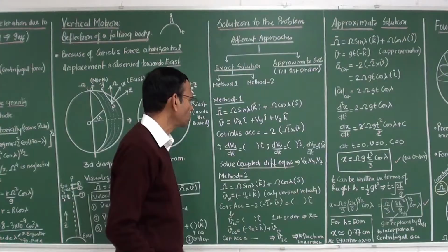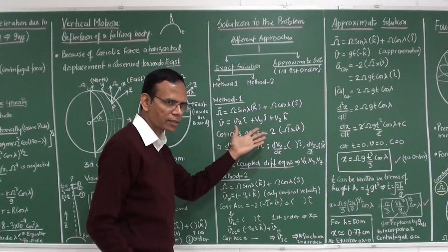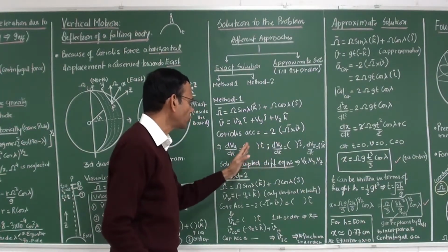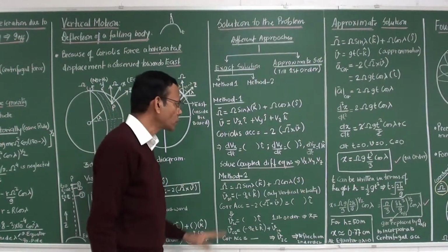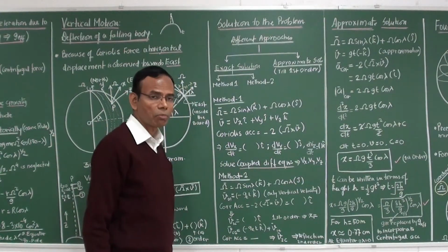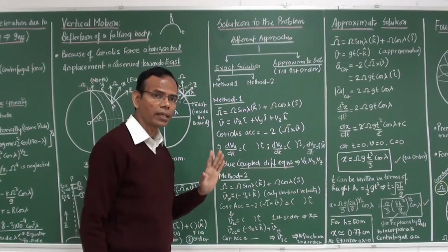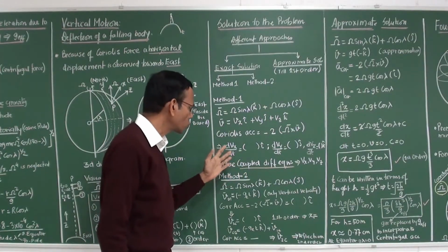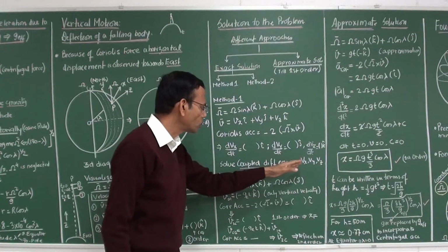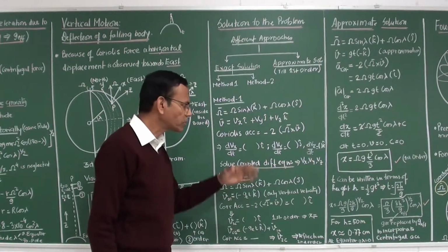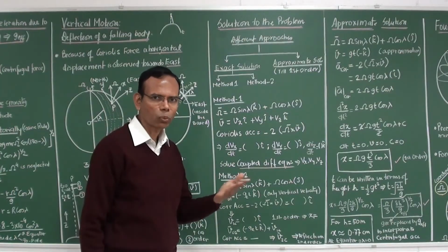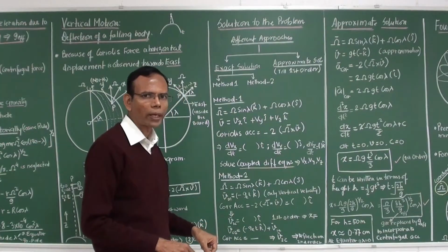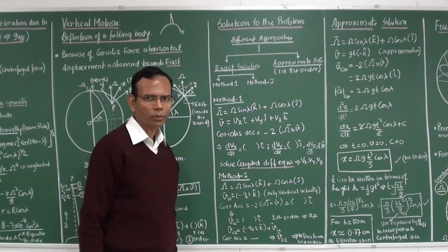So three equations we have to write, because this is an acceleration term, Coriolis acceleration. From Coriolis acceleration in the x direction, in the y direction, in the z direction, we have to write according to the unit vectors. So you are getting three different equations, but these three differential equations are coupled with each other. And it is not very difficult. You can solve it, three equations and three unknowns. So you will get Vx, Vy and Vz. From there, you can find out the deflection. That is x and y you can find out, because that is what we are interested to find out.